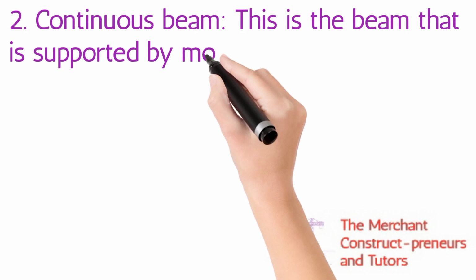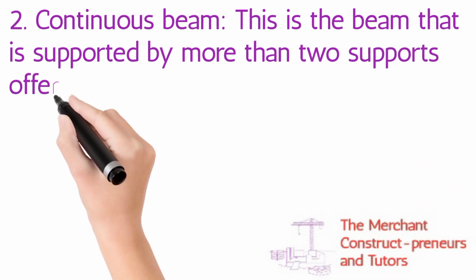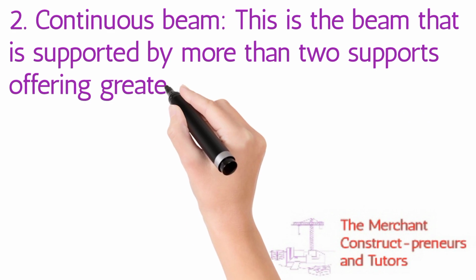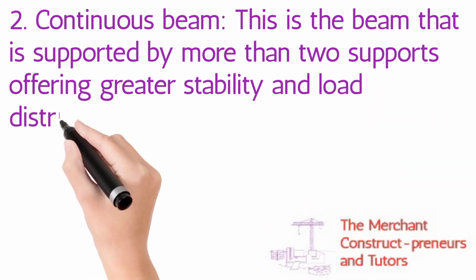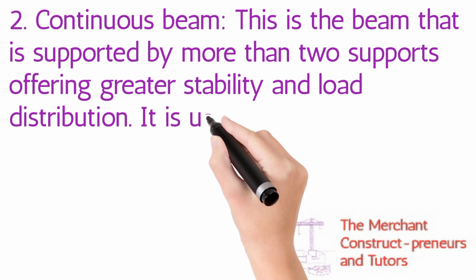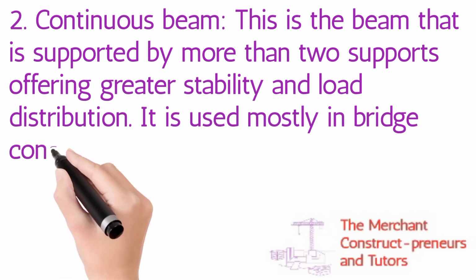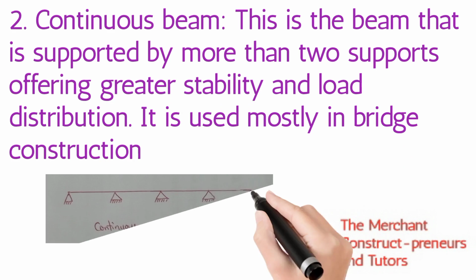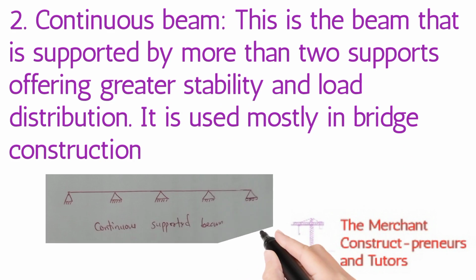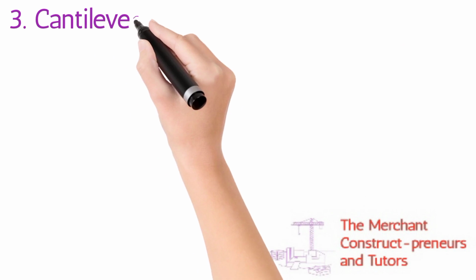Now looking at the third classification, based on the support condition, simply supported. When it is supported at two ends, one side is pinned, the other side is roller. So it allows for rotation and translational movements, as shown in the diagram. Then for the second part, based on the support conditions, we have three classifications: cross section, position of reinforcement, and then the support condition. So the third one, that's what we're looking at, and then we have the simply supported, which I already explained.